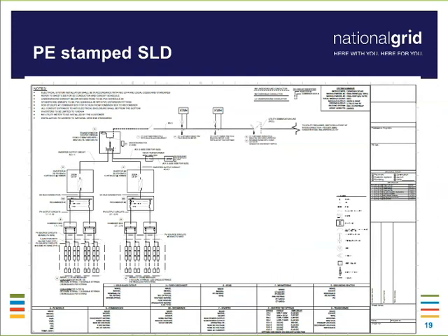So, all right, single line. The single line drawing is very important to everyone involved in the design, as it is the electrical representation of the equipment arrangement. The single line provides us with a lot of valuable detail. It's going to show us the electrical path for all the equipment so we can make sure that everything lines up as expected. Again, this is a drawing that would need to be stamped because at this point in the process, we have finalized the design, right? We want to move towards the construction phase.